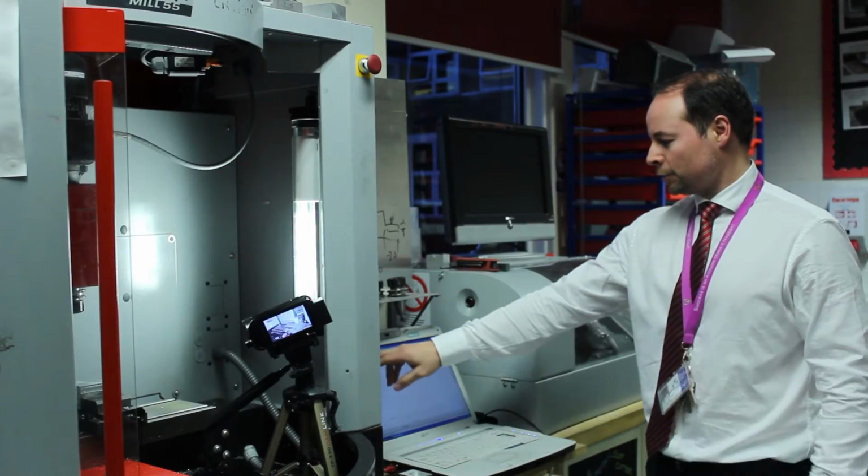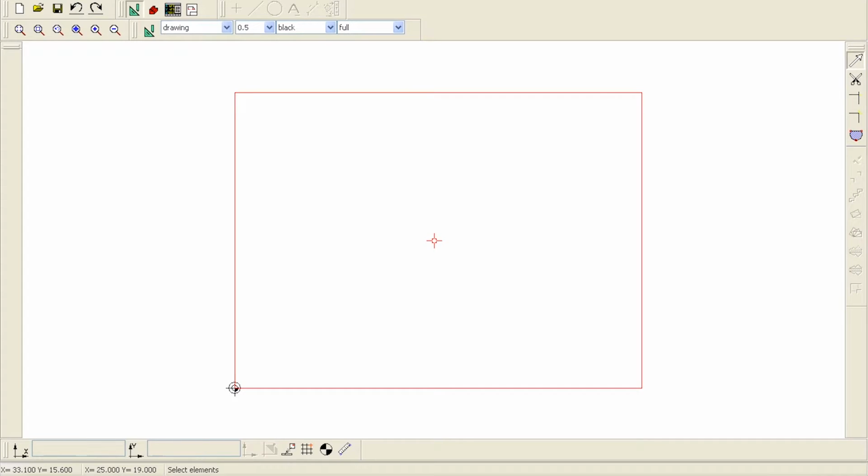First thing, you're going to need to draw the part. Draw the part you're going to cut out, the hole in this case. Now, if you notice, I've got this on the draw on CAD, and there's none of my tools available. If this happens, make sure your cursor's here, and right-click, and all your tools will reappear. That's something that could catch you out.